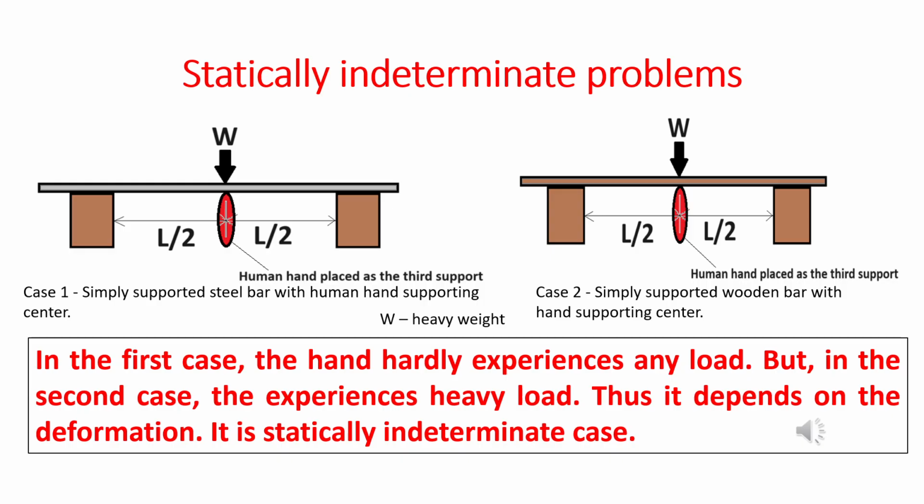This type of structures are called statically indeterminate structures, where the load does not just depend upon the equations of statics, but also upon the stiffness of the structure and the deformation of the structure. So these type of structures, where the support reactions are dependent on the deformation of the structure, are called statically indeterminate problems.